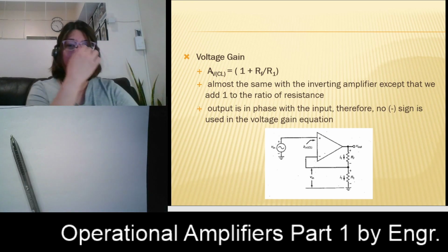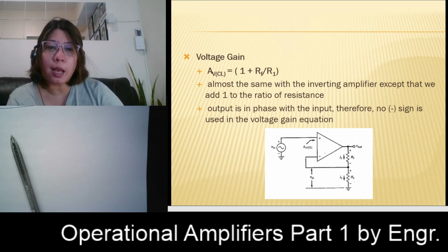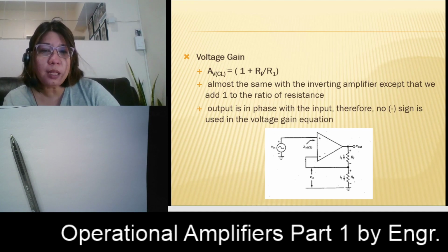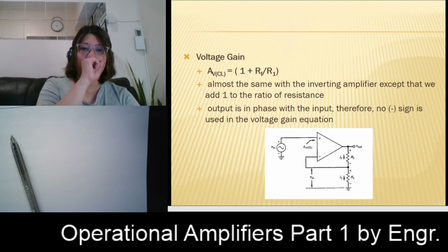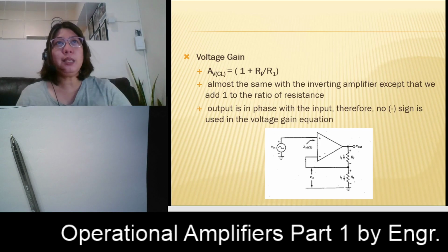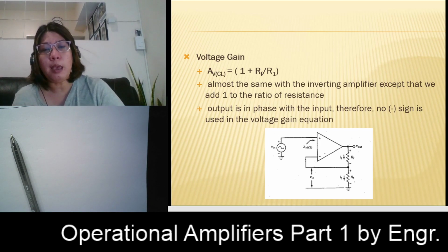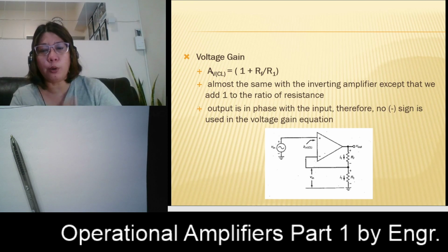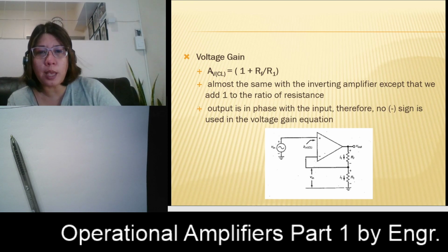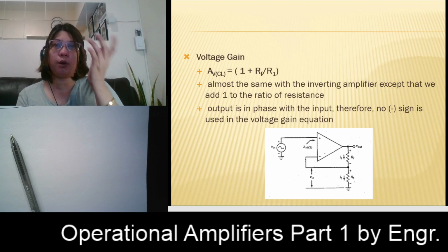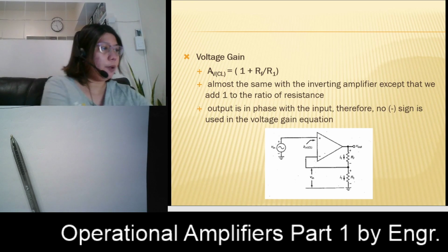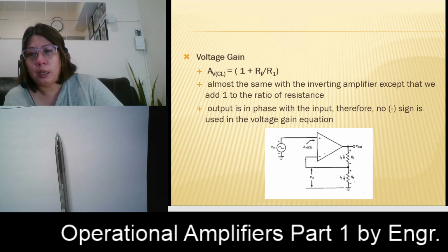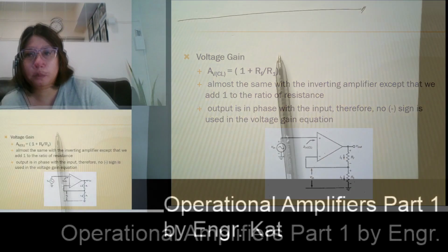As you can see, whatever your voltage across your R1 here, that is equal to Vin because V1 minus V2 is always equal to 0. And because of the virtual ground, we know that no current must enter your inverting input. So your current I1 here is just equivalent to our current I1 here. They are just equal because of the virtual short or the virtual ground. So if we're going to elaborate this one, what do we have?